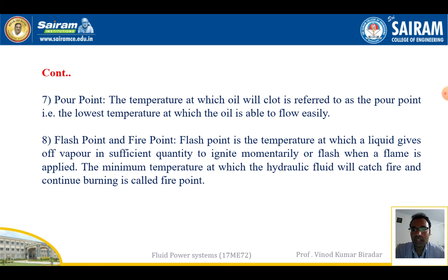So next one is flash point and fire point. Flash point is the temperature at which the liquid gives off vapor in sufficient quantity to ignite momentarily, or flash, when a flame is applied. The minimum temperature at which the hydraulic fluid will catch fire and continue burning is called the fire point. So this is the main difference between the flash point and the fire point.